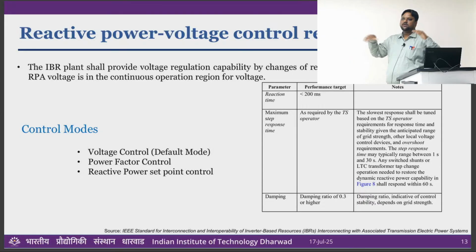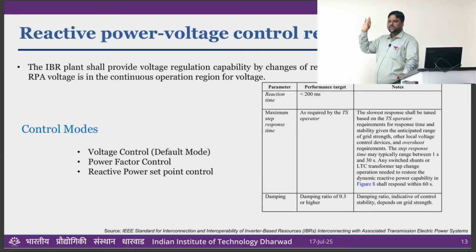Okay. IBR control, all we discussed yesterday, following grid forming, internal voltage current, those will be going on. But being a plant, at the plant level also you have to maintain these things, because at the end of the day you have to inject P and Q at a stable V and F to the grid. Okay. V, when I say voltage, F is frequency.